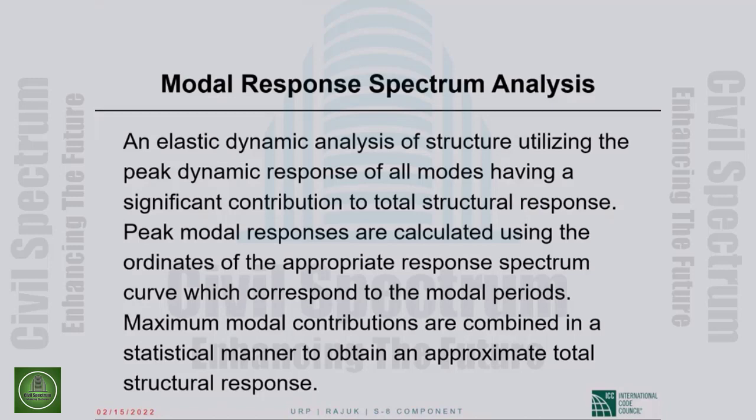An elastic dynamic analysis of structure utilizing the peak dynamic response of all modes. This is important. In modal response spectrum analysis, we are concerned only about the peak response of the various modes, not the history of response. Okay? Our sole preoccupation is with maximum values.